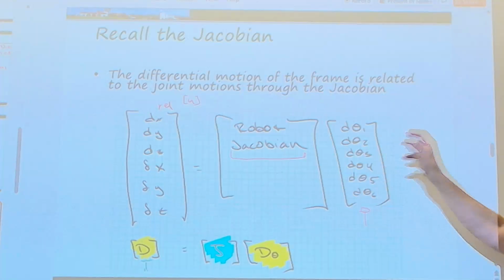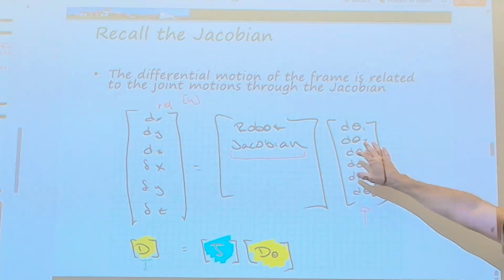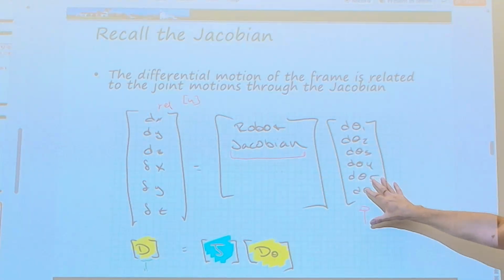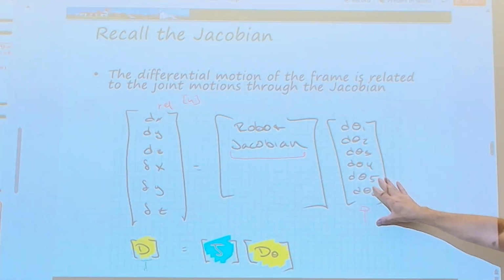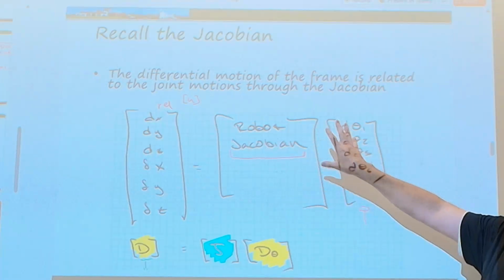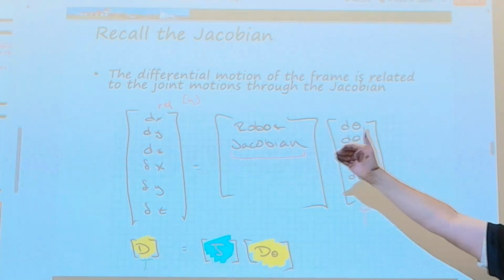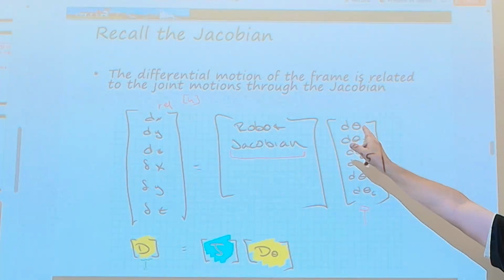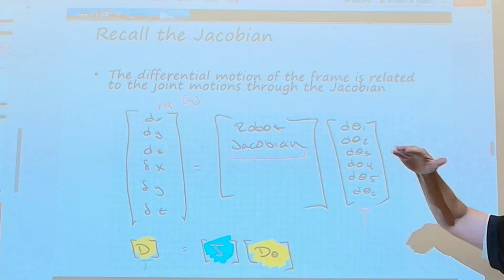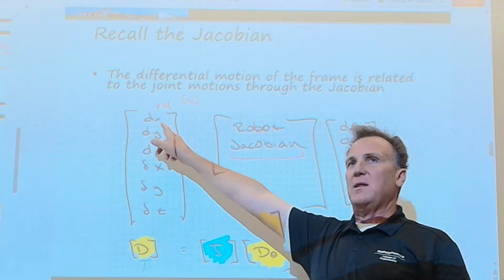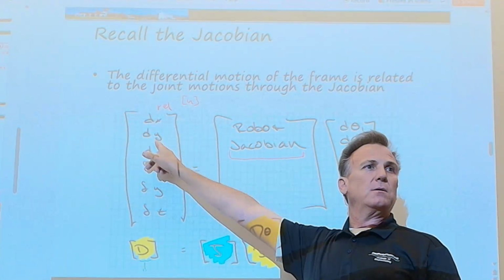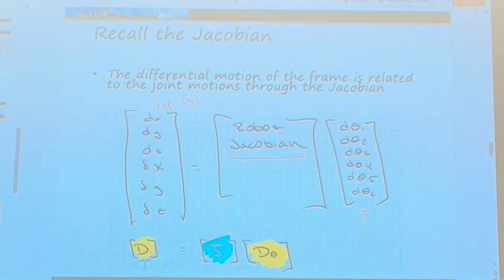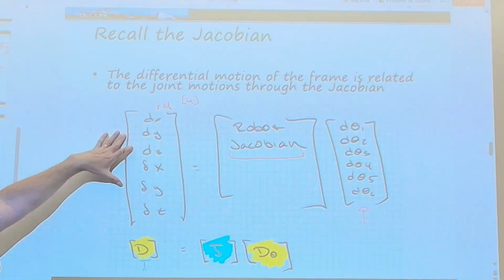Velocity. So if I have a controller set to theta, then this is still controlling to theta dot, right? Because I can only control motor velocities, like you all said. But if I have a PID that's also controlling an outer loop to theta, as well as theta dot, and I want to make theta the dominant, what do I say? This could go above and up and down, right? But if I go up and down, then that means these velocities will change. So yes, I might have gotten my theta, but I did it sacrificing all of this.